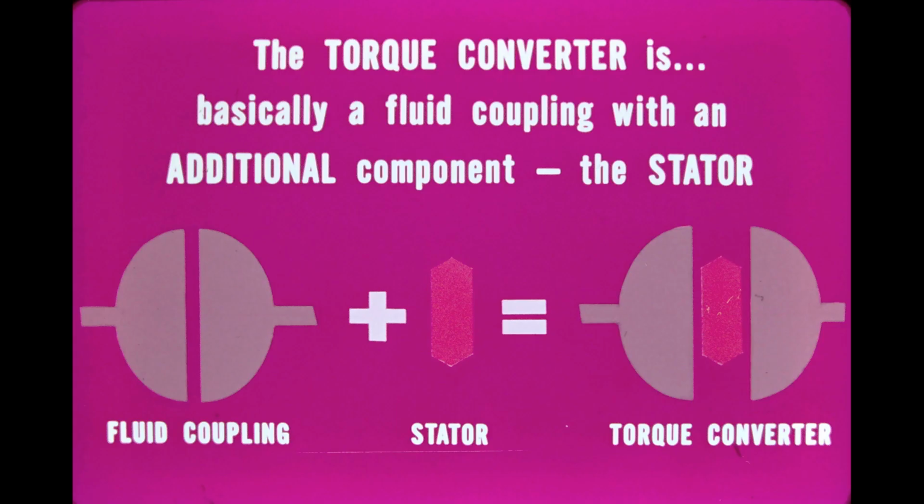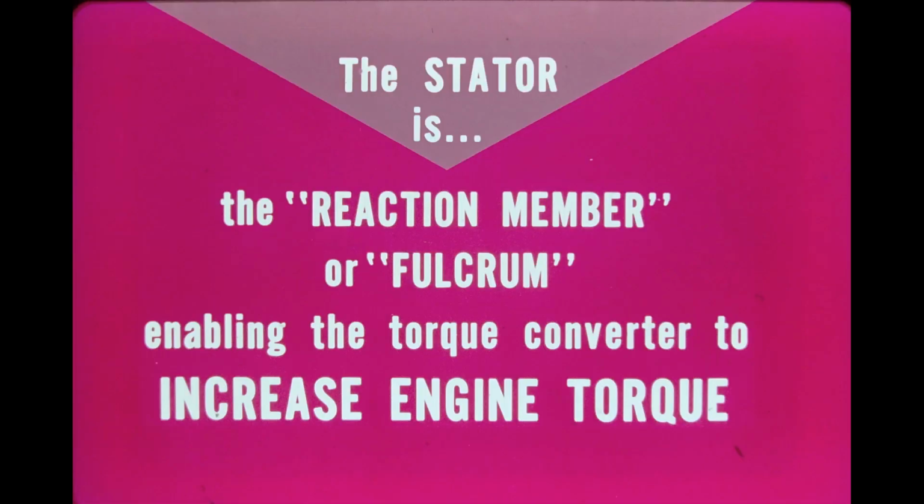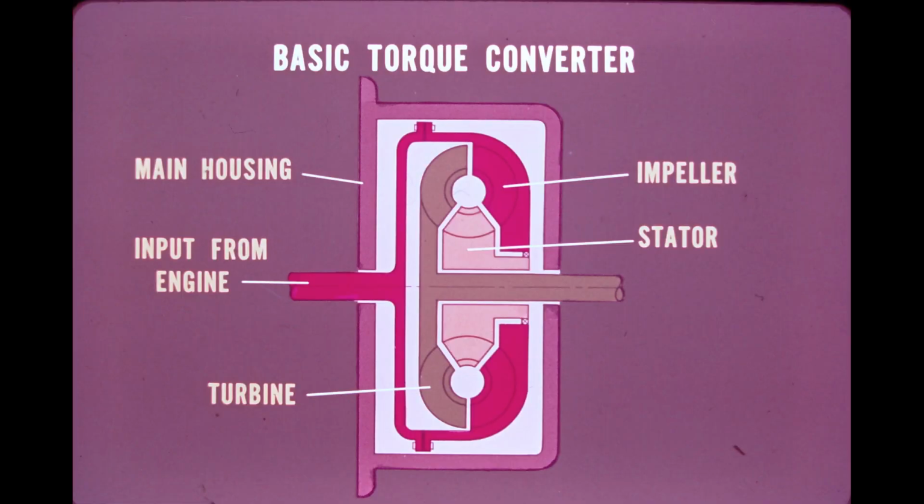Construction of a basic torque converter is essentially the same as the fluid coupling, except that the converter has an additional component, the stator. The stator is the reaction member, or fulcrum, enabling the torque converter to increase engine torque. More about this in a moment.